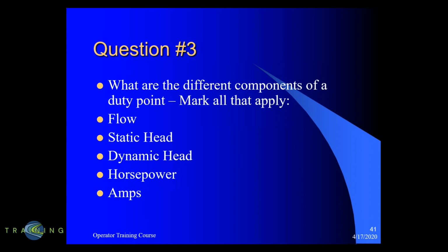And then, yes, per Cody's question earlier, back pressure in the line you're pumping into will be part of that head requirement that'll have to be also considered.